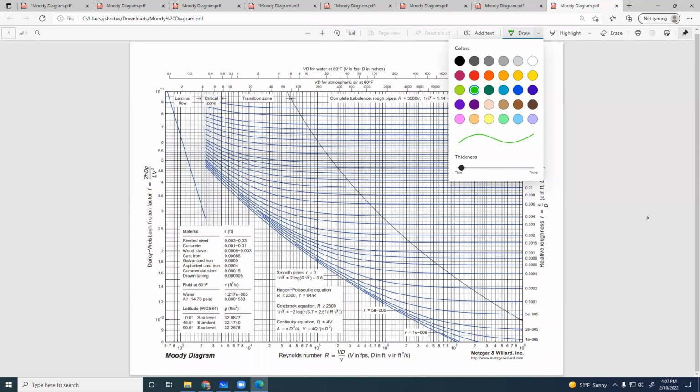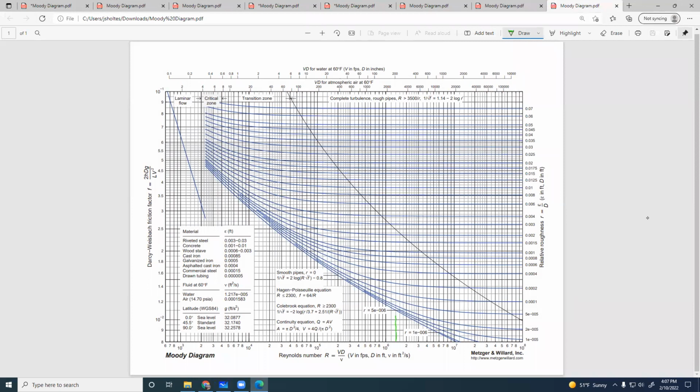Okay, so here is 1 times 10 to the 6, 0.2, 0.4. Take that all the way up. And then here was our original E over D. The way we do this is you take that flat line and then you start to curve it up and basically do a visual linear interpolation.